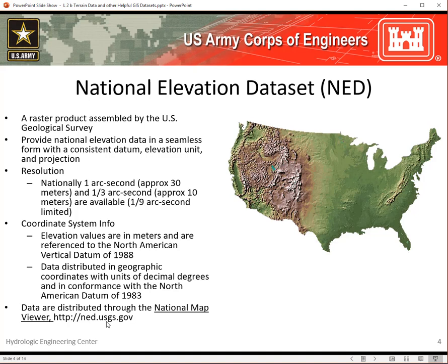Whenever you do download that data to your computer, note that the elevation units are in meters. That's for the entire United States. And also the terrain data that you gather has not been projected. It's unprojected terrain data. And so you're going to need to run through a few steps outside of HMS to process the terrain data before you start using it within the GIS delineation tools.